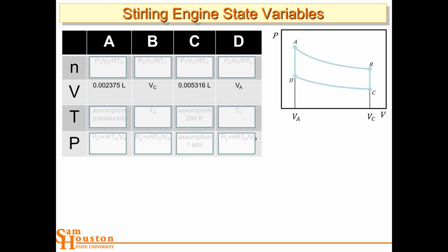You've got to have some measurements of your engine. And that's why for automobiles, they talk about displacement. So like a 5-liter engine or a 3-liter engine, that's the displacement that all the cylinders displace. And then one value that's not really advertised, I don't know why, it's just as important, it's the compression ratio. So as you compress that cylinder, you compress all the gases and then you light them. That's another critical piece of the parameters.